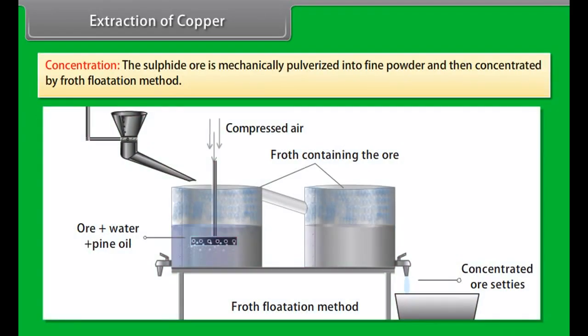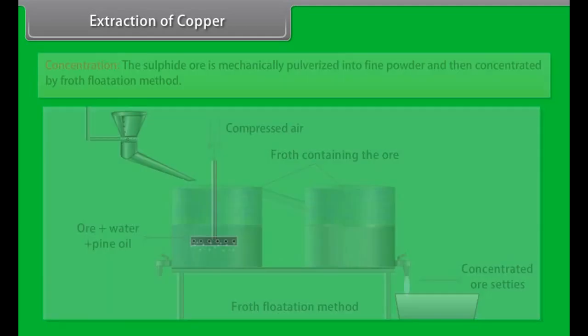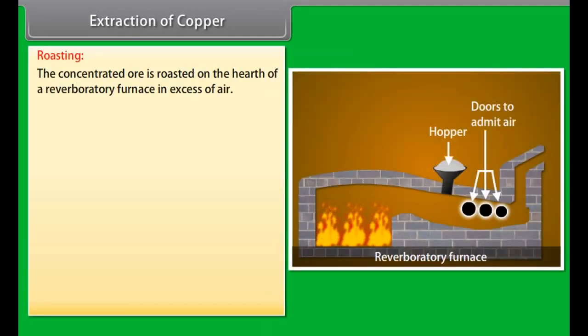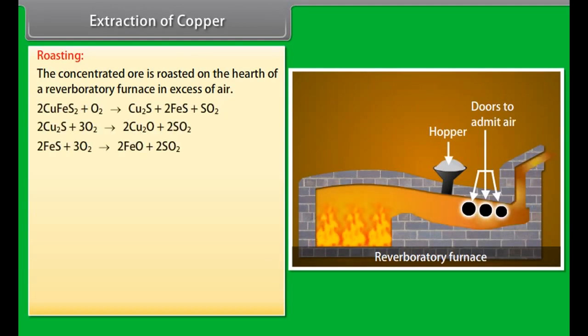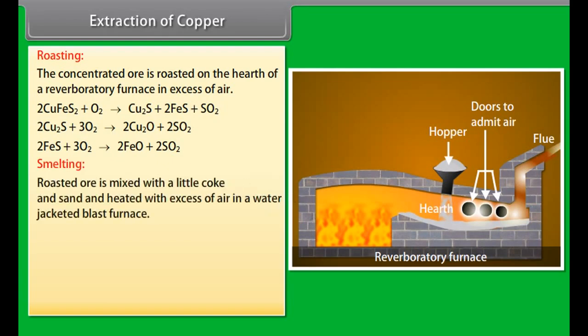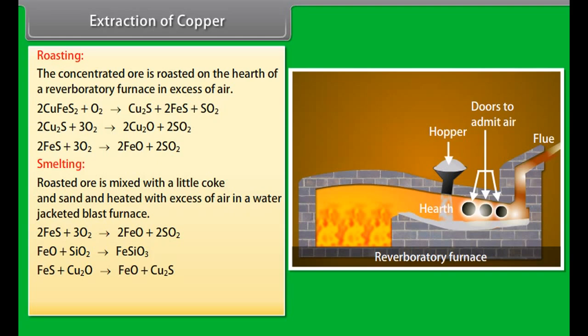Lower zone of reduction. Final reduction occurs between 1000 degrees to 1200 degrees Celsius in the central region of the furnace. Carbon obtained by dissociation of carbon monoxide combines with iron, and impurities also get dissolved in molten iron. Zone of fusion. Here, temperature ranges from 1200 degrees to 1500 degrees Celsius.